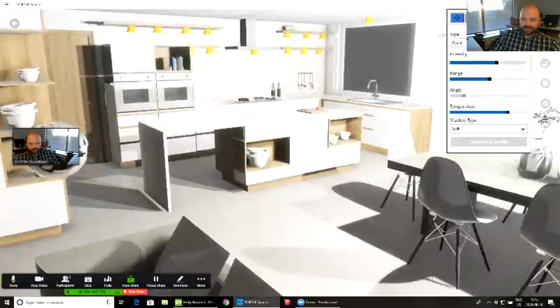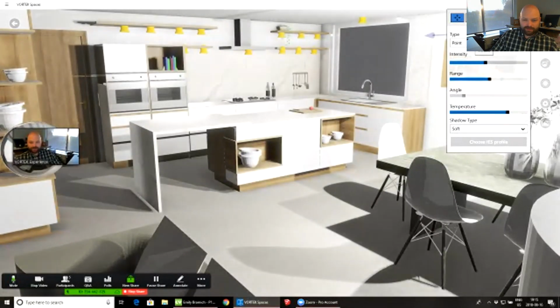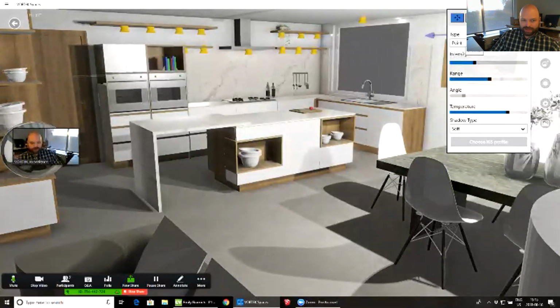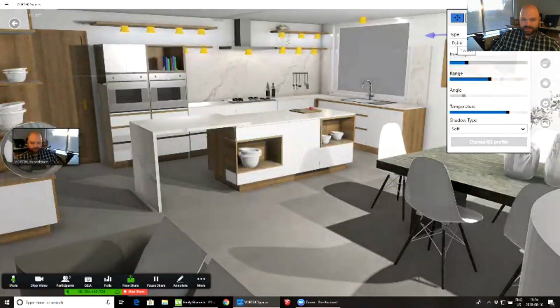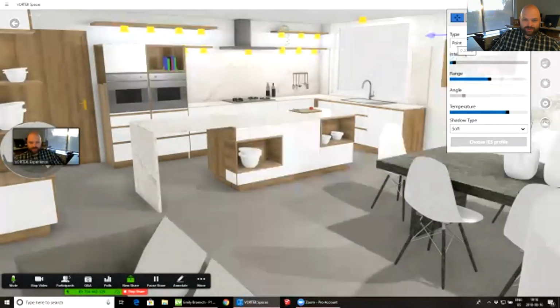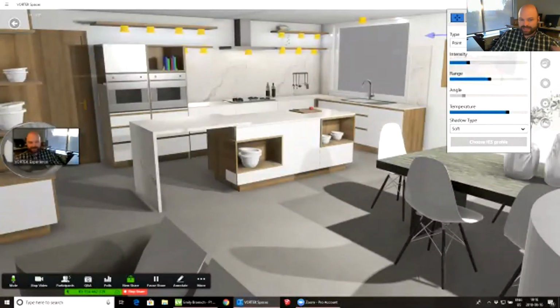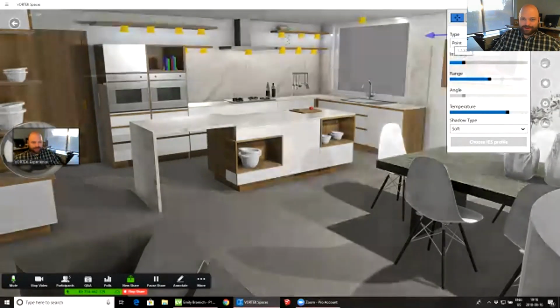And if I take those lights and bring down the intensity, you see the software is always readjusting the overall level of the room as I go down. So that's basically what the eye adaptation tool does. Otherwise, if we didn't have that and I was doing that exact same thing with those lights, everything would just become a big bright white nothing. So this is a very nice tool, but it can also play tricks on the projects.